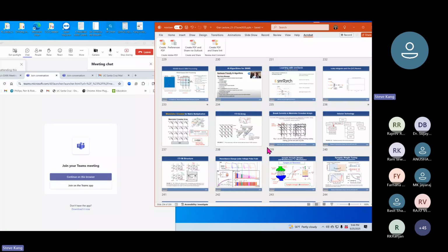If you use wire that is too narrow, it will introduce lots of series resistance. So you have to be careful that this resistance, compared to the memristance value, either low or high, is much smaller. In many analyses, the drain-to-source resistance is neglected in simple analysis, but it is there. Thank you. You're welcome.